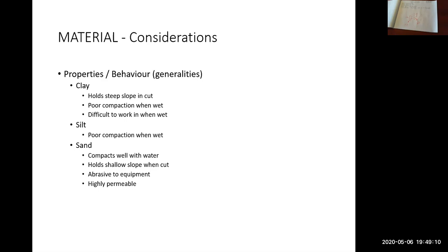Material considerations. So properties of materials, just in general. Silts and clays behave quite similarly. We'll look at a photo of this on the next slide. So with silt and clay, when you excavate a trench, the trench walls can be quite steep. It's not going to cave in on itself.